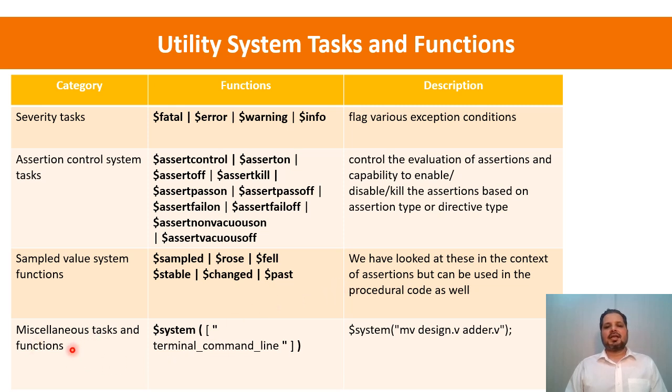There's one miscellaneous task and function called $system. So $system is one of those, I would call it a magic function. You can actually run a Linux command using this. So you can say $system, move something to something. Whenever this particular call gets executed, it will execute this move command on the shell. So when you are doing some automation, you will find the $system function to be useful.